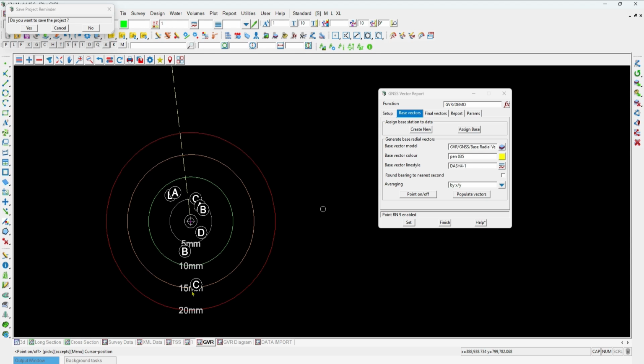We've done a bullseye for you, so you can see the spread and how far from the location average each surveyed position is. The cool thing is you can have a look and go, well, there's some error here. Potentially between the two C's there's a bit of a pole error. So you can start removing some of these observations that you consider not good enough.